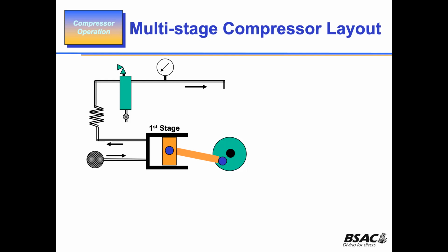And so these compressor valve cylinders have what they call plate valves on them. Most have plate valves. They don't go for sophisticated. All the plate valve is that when you go into the suction and you pull the air in, the inlet valve opens, but the air that's already gone in pushes the outlet plate closed.